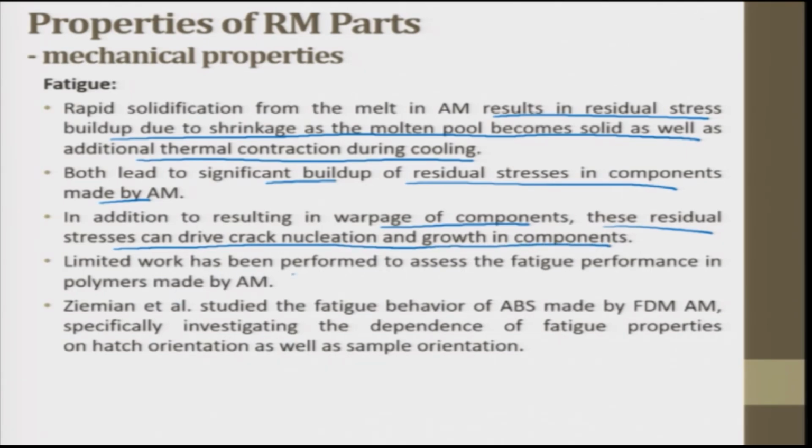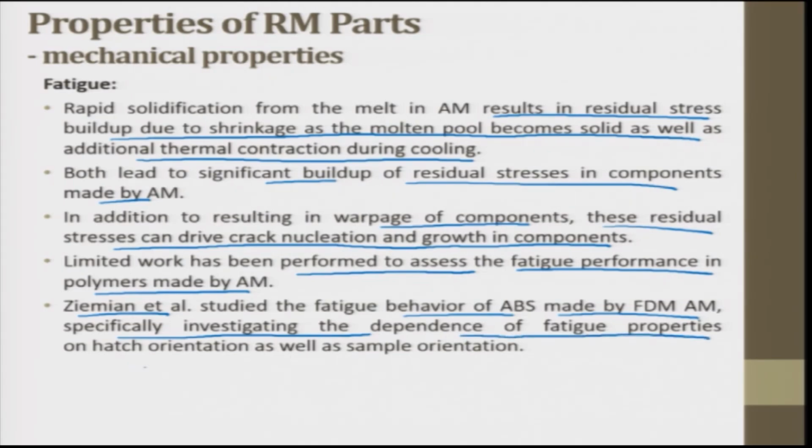Limited work has been performed by researchers to assess the fatigue performance of polymers made by additive manufacturing. Zeman et al. specifically studied the fatigue behavior of ABS made by FDM additive manufacturing, investigating the dependence of the fatigue properties on hatch orientation as well as sample orientation.